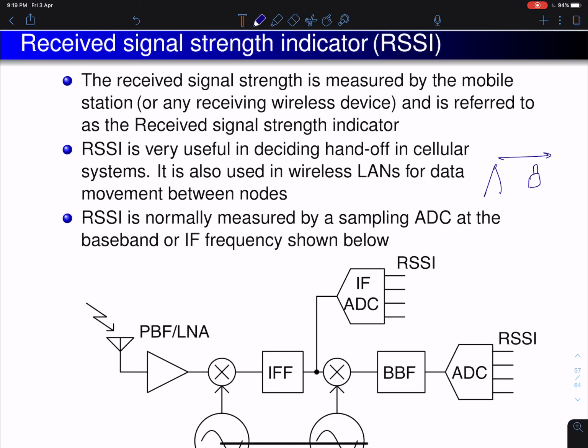Okay, so for this, both the cell phone and the base station, in the past, in the beginning, the base station used to do all the calculations. So the base station estimates what we call RSSI, received signal strength indicator. Okay, it computes a received signal strength indicator. So meaning it somehow computes the power levels. Here, what I am talking about is the computation made by the base station. The base station tries to estimate the power that it is receiving from a cellular phone.